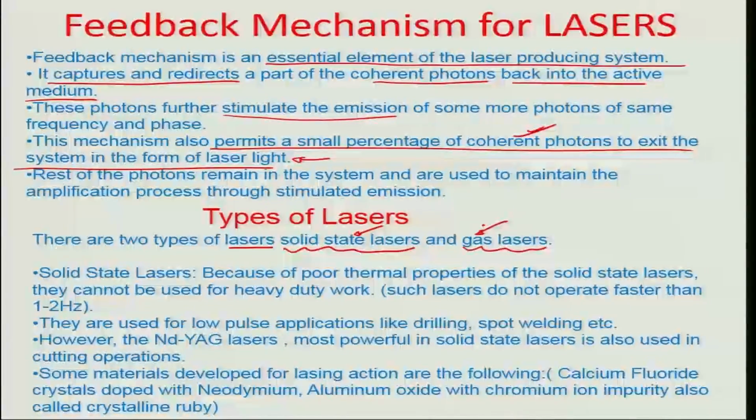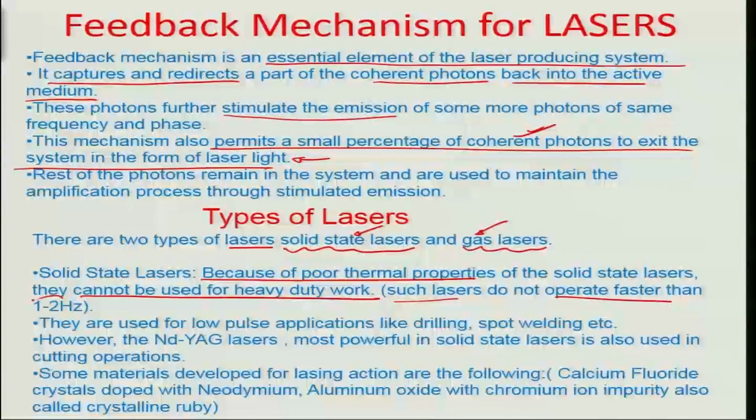Typically solid state lasers, because of poor thermal properties, cannot be used for heavy duty work, so that has to be always remembered. They are very slow lasers, they don't operate very fast, maybe the operational frequency at the most is about 1 to 2 hertz. They are however used for some low pulse applications.